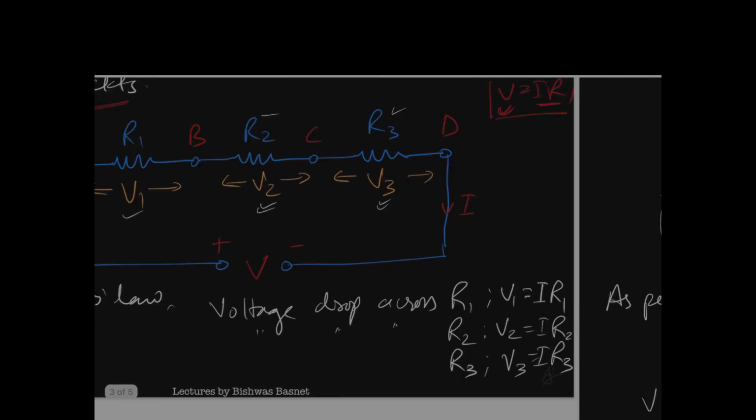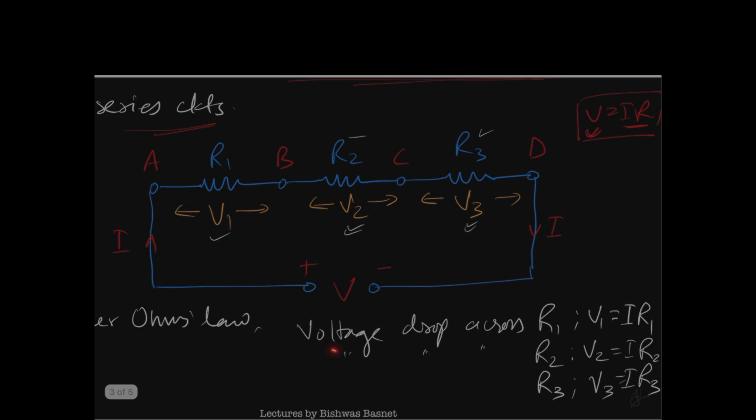So if that is understood, what I can write is the voltage drop across this particular element R1, by recalling Ohm's law. Since the name is V1 for that, I would write V1 equals the current flowing through it. And definitely there's only one path for this current that we have assumed for the whole circuit, so it is definitely going through R1. So the current flowing through R1 is I, correct? Times R1, that comes from Ohm's law. Why am I writing R1? Because we are trying to calculate V1 for R1. So V1, the voltage drop across R1, from Ohm's law,